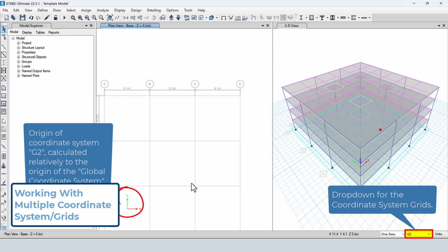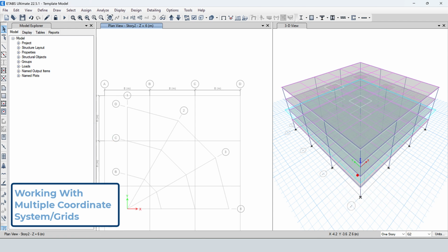On the other hand, you may be wondering why the cylindrical grid lines are not displayed. The reason is that we've set the range of stories to which this grid system pertains to be only from story 2 to story 3. If we display a plan view of story 2, then the cylindrical grid lines are presented as expected.